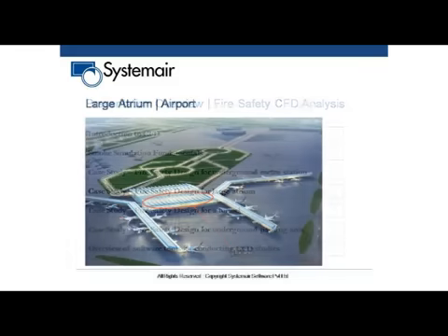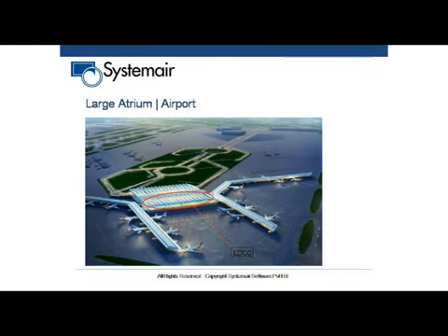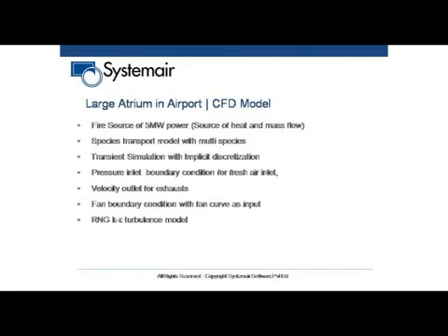This is an international airport, a new airport upcoming in New Delhi, and there is a large atrium where there are check-in counters in each area, and we did a simulation with a 5 megawatt source of fire. 5 megawatt is typically a car fire, or maybe a bit more than that. So it was a reasonable size of fire. Species transport, these are the CFD terminologies that we used for that particular case. This was the 3D model.